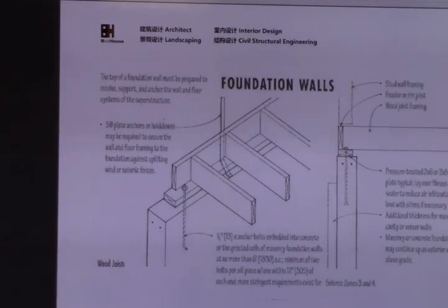This is a typical section for the foundation, and there is some steel plate and framing relationship and hold down. Why do we need the hold down? Here, it's a plate embedded in the concrete, and the plate is nailed to the wall. It's usually at the corner. Every building has 4 corners, depending on the shape.